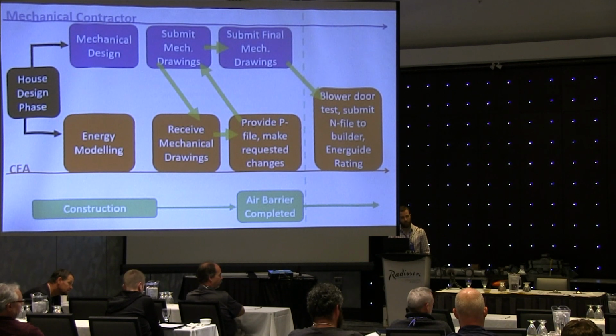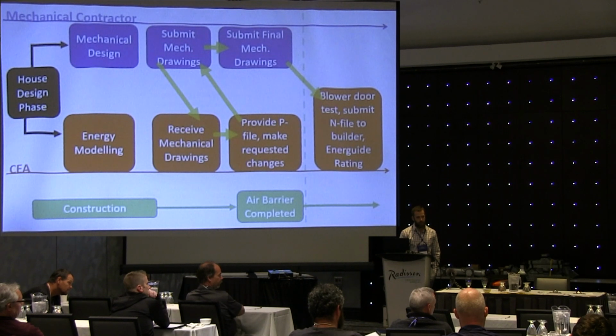There's a huge increment of flow difference between using a 4-inch branch in Mrs. Smith's bedroom and a 5-inch and a 6-inch. There ain't no such thing as a 5.5-inch duct. We are not dampering any of these branch runs right now because you can't, because all the duct is boarded over. So it's left to Mrs. Smith to fine-tune with grills, because that's the best we can offer. So be very, very careful if you're going to right-size as the provincial and federal governments would advocate, because you've got to be cautious when you get that close to the margin.